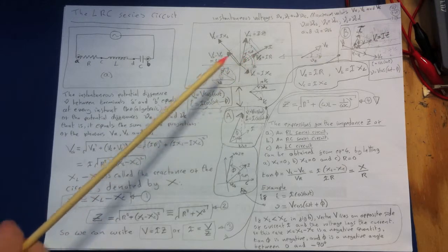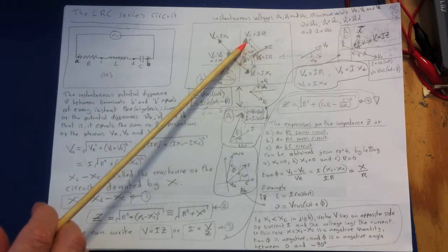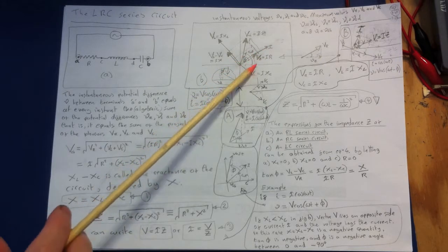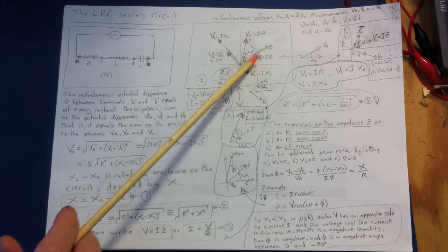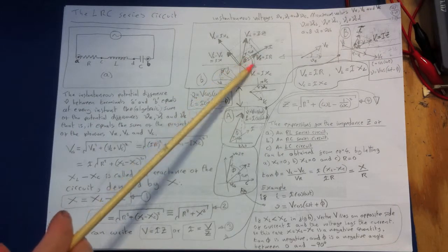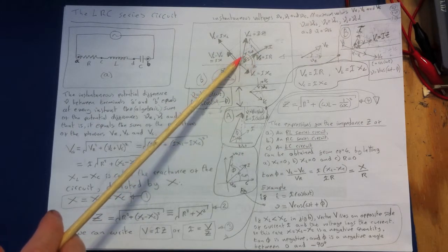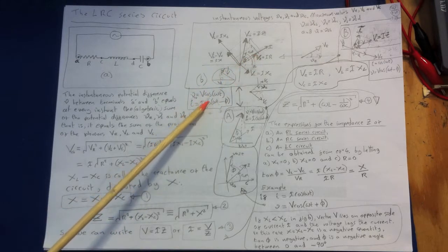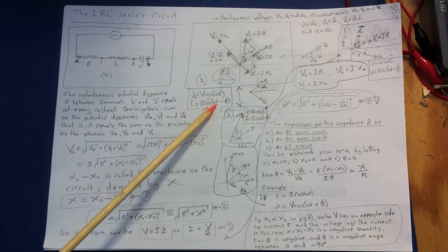So that means we know here that the current is behind the voltage. So we know that that's lagging. To get this angle, which is that angle to there, we've got to go all the way to ωt, and then we've got to subtract. We're going to come back and subtract to get us back here. So if we use cosine for that as well, that's simply ωt minus theta.